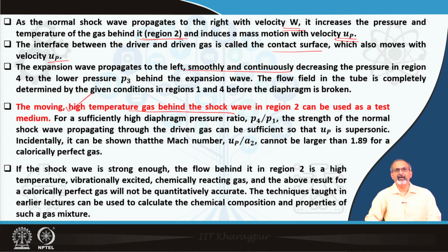For a sufficiently high diaphragm pressure ratio P 4 by P 1, the strength of the normal shock propagating through the driven gas can be sufficient so that the u p becomes supersonic, and therefore, high temperature supersonic test conditions will actually be created in the wake of the shock.